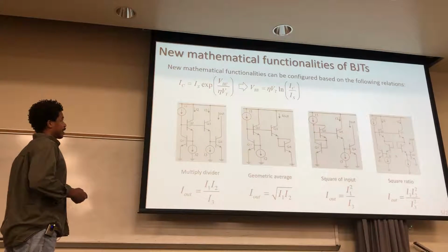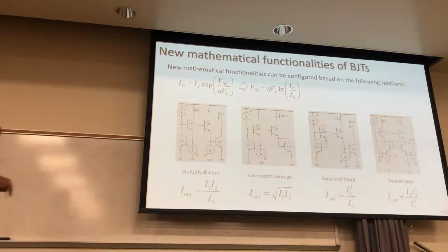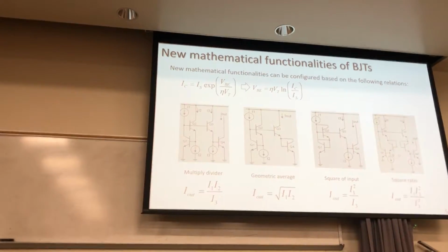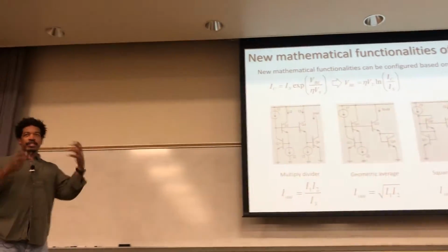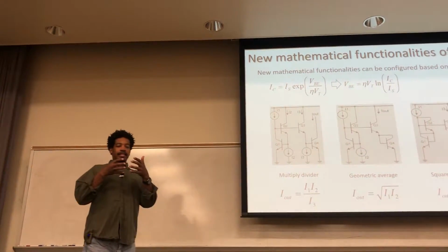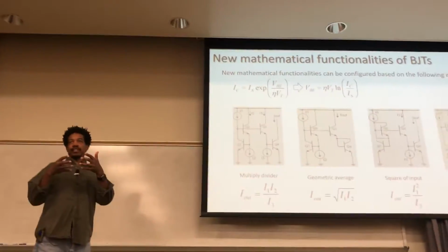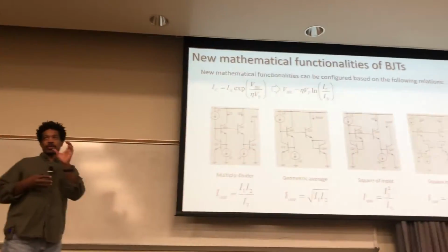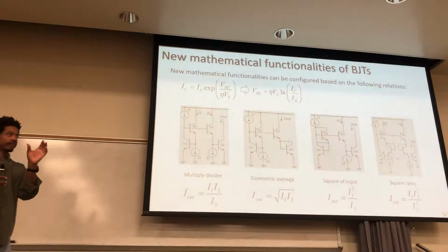He gave this to us because what we were trying to do is some really fast feedback for MEMS devices. The kind of feedback we wanted was to look at the state of the MEMS device and then feed back a signal that had been processed from its state. We looked at the capacitance, because for MEMS, unlike circuits, the capacitance is always changing, and it tells you where the MEMS device is, its trajectory.